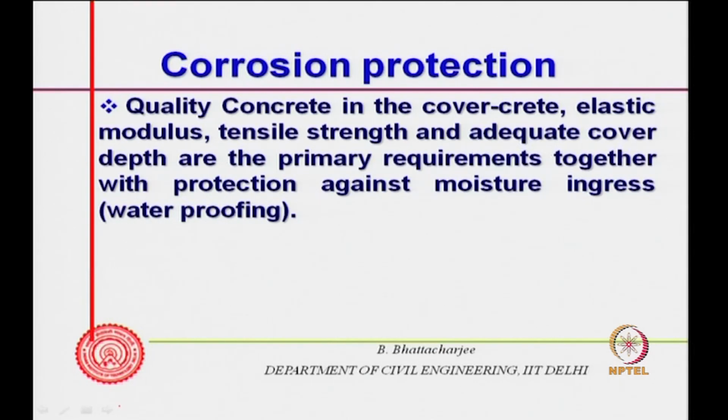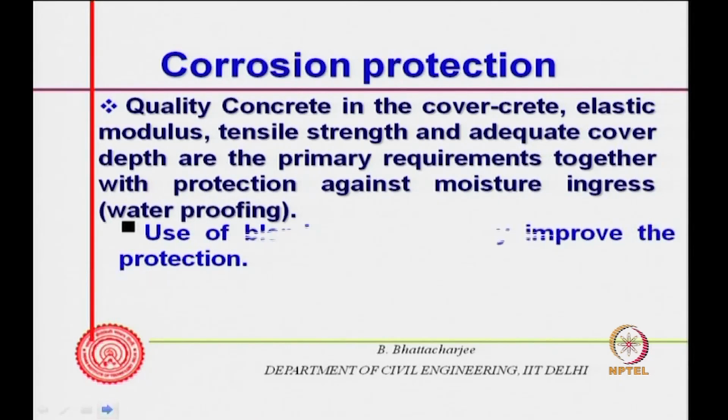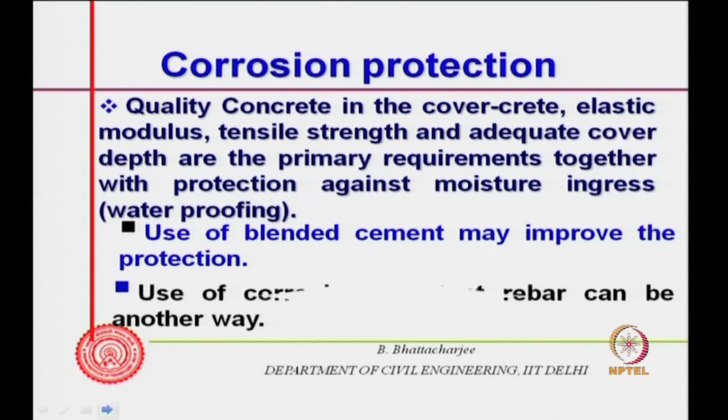but moisture is one thing which you should keep out. So, good waterproofing. Use of blended cement improves the protection, because blended cement exhibits better resistivity of concrete. Sometimes they improve protection, even though depassivation time may not increase in carbonation, but still overall it might provide better protection.